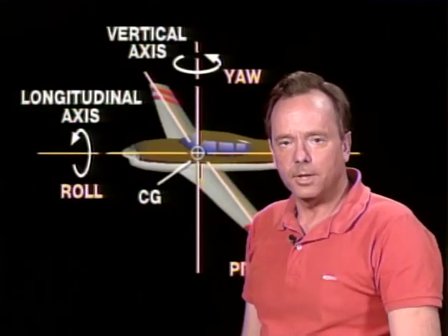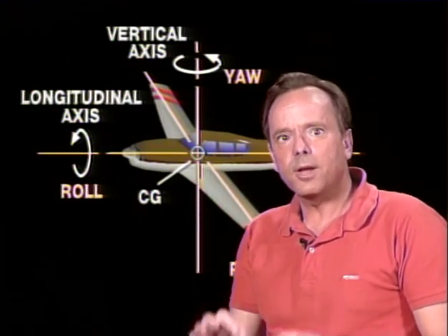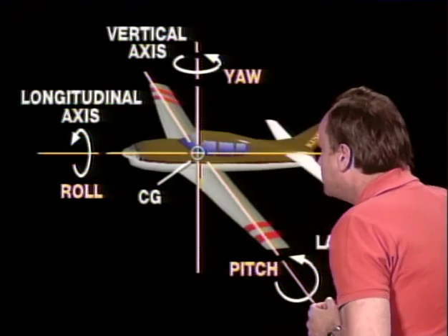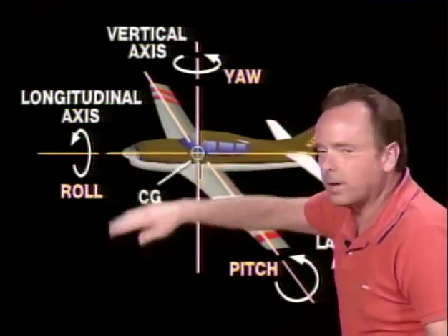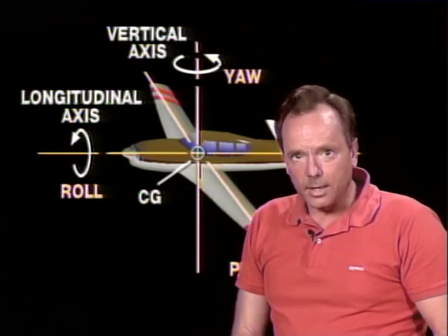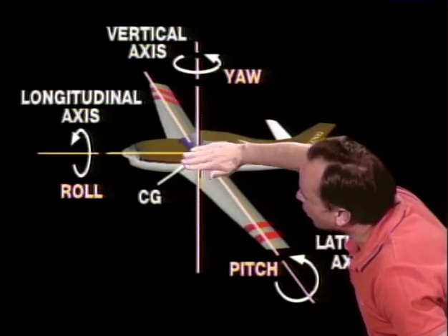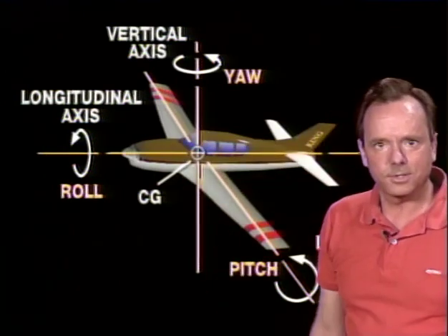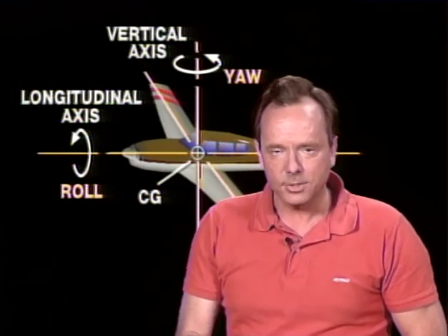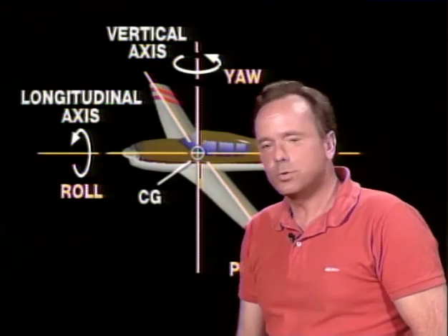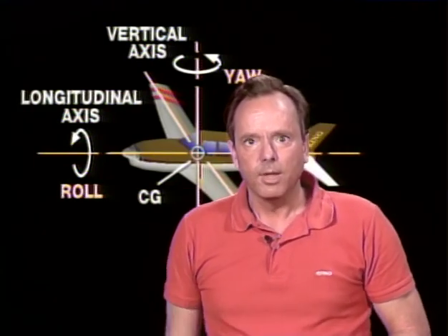Let's talk about stability. And to lead off, let's talk about lateral stability. And lateral stability is stability about the axis which runs parallel to the line of flight. Which one that is that? That's the longitudinal axis. The longitudinal axis runs parallel to the line of flight. Lateral stability does not refer to the lateral axis. Lateral stability refers to roll about the longitudinal axis. Now, it is very, very confusing, but that's why they ask you questions about it on the FAA written exam. So lateral stability is stability about the axis which runs parallel to the line of flight, and it's referred to as lateral stability.